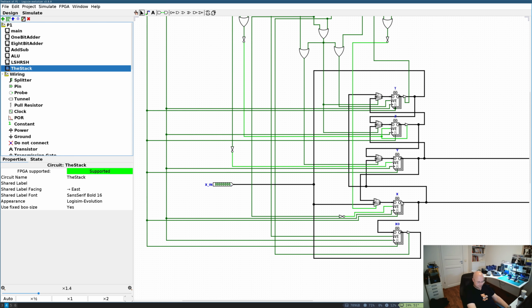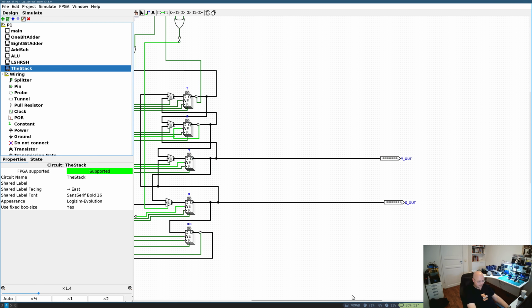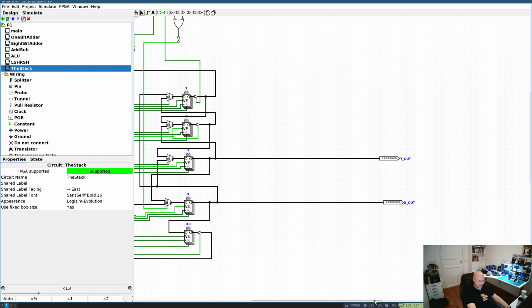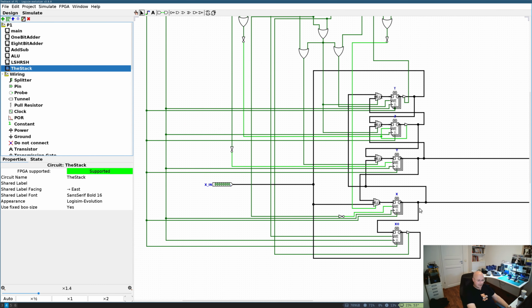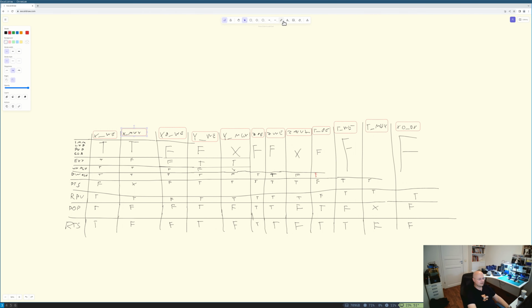And this way, with the clock, we say, hey, on the falling edge, the value is presented on the output of the register, and all the sequential circuits are going to update the signals. On the rising edge, we expect our signals to stabilize, and we sample those signals and store them in the register.